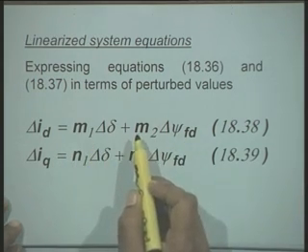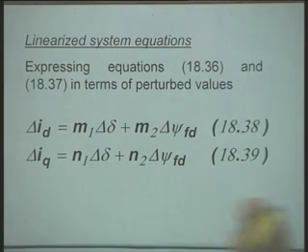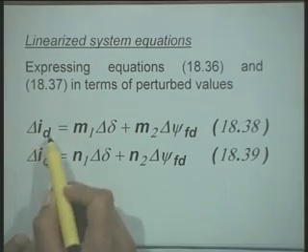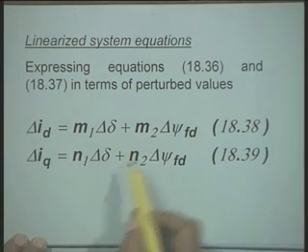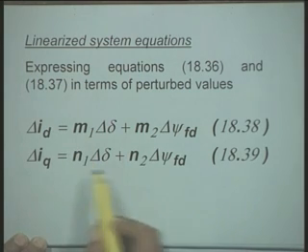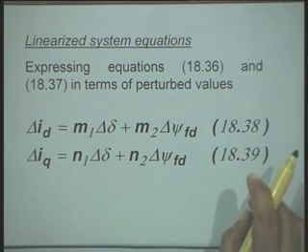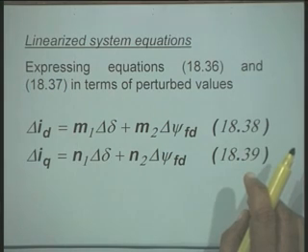These M1 and M2 are the quantities which depend upon the synchronous machine parameters, the line parameters, and the initial operating angle of the system, that is delta naught, the operating condition of the system. That is, these two equations, which are the incremental equations for the direct axis current and quadrature axis current, are now written in terms of the state variables, and these coefficients are functions of the system operating condition and system parameters, which include the synchronous machine parameters and the line parameters.